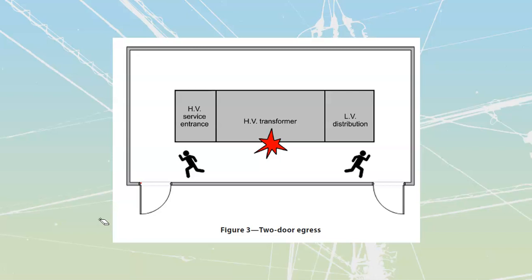If in doubt, if the electrical room is warm, talk to somebody about the fact that this thing should be cooled down, because it will cause long-term issues, not only failures of the equipment, but also a lot of nuisance issues where breakers are going to trip when they're not actually close to their limits.